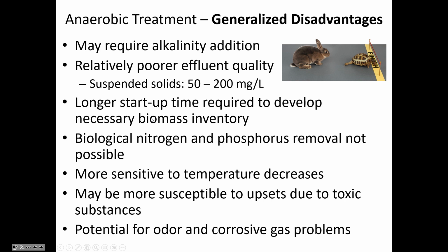Finally, the gas is not only flammable, but hydrogen sulfide, when it forms, is corrosive, and so you're recirculating this gas to mix the anaerobic waste in that digester, but it can break down the pipes and the pumps if it has hydrogen sulfide in it, and also the odor is bad, but hopefully the odor isn't an issue. The odor is only an issue if gas is leaking around the seals of the digester, but the corrosive gas accumulation can be a problem even if things are well sealed.